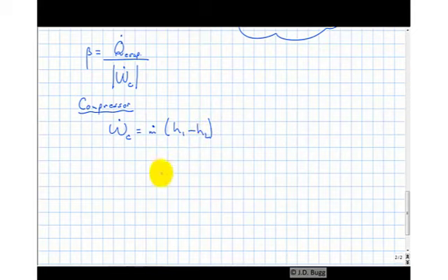Well, to get H2, remember that the compressor is isentropic, so S1 equals S2, which we looked up already when we looked up the enthalpy originally for point 1, so that's 0.971481 kilojoules per kilogram degree Kelvin. And also, P2 is 8 bar.